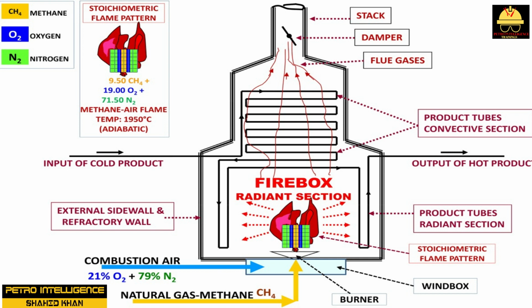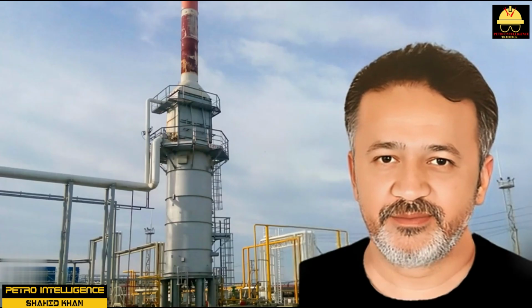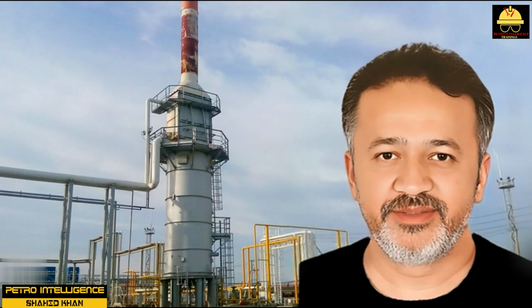The floor of the process heater has a 6 inch layer of heat-resistant castable, capped with high-temperature fire brick. Four ceramic high-temperature refractory blocks are positioned around the burner. The refractory system can withstand a wide range of high-temperature conditions. The refractory layer can be over a foot thick. The convection tubes in the upper section of the furnace have a variety of return bend designs.